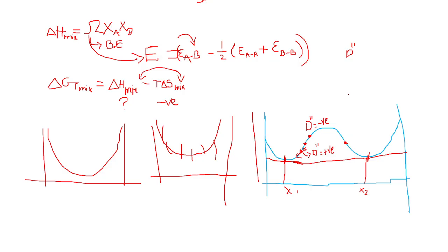So that is about the spinodal decomposition. And the binodal and spinodal decomposition, the only difference is about the free energy changes. How the slope of the free energy versus composition curve changes: for this it is positive, and for that it is negative. So even if I try to disturb my composition slightly, from here to here, that's how it forms. Once I quench my sample, because of a small fluctuation inside the composition, the change will be so much negative.